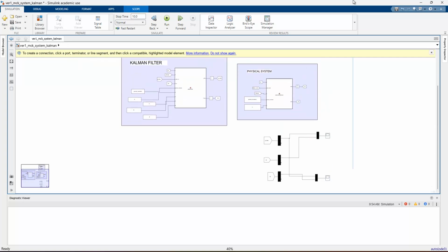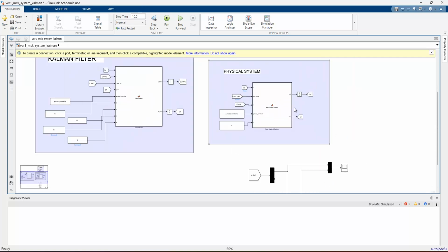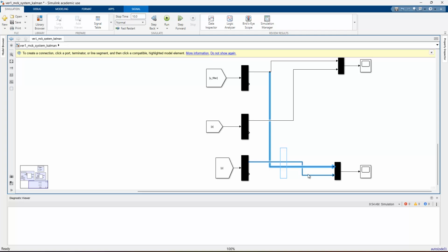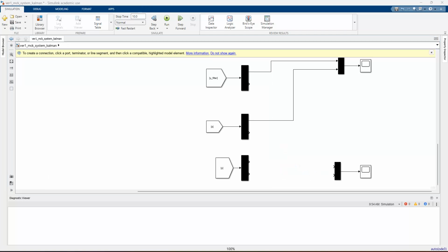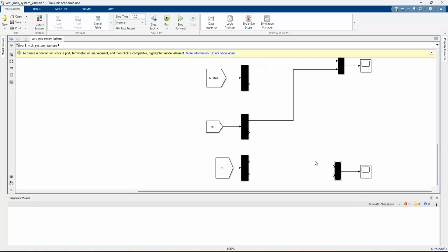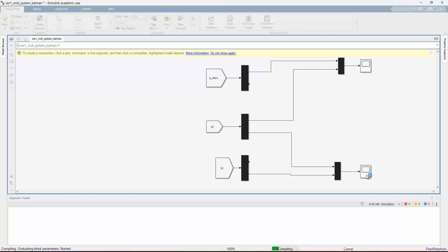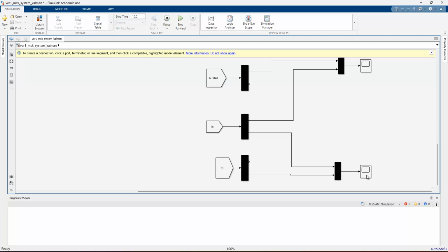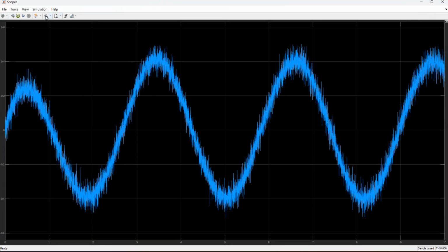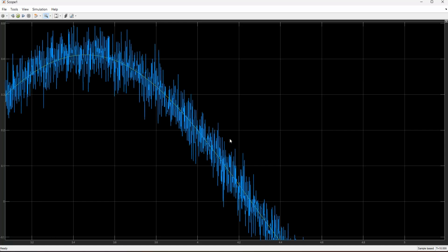Okay, guys? This is important for our study, and so we can remove this connection in here. Okay, the Z2 body or the velocity is compared with this one right now. If we run this code, then we will have the velocity comparison in our code. Just see that in our code the yellow one is the Kalman filter response, the other one is the measured signals in here, right?